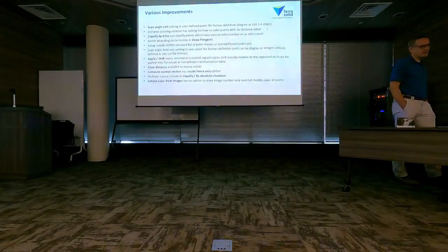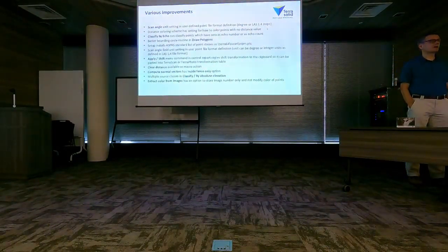process drone data and you have single markers and you solve an XYZ shift to match the data with single marker control points, when you do the apply shift, the software now places a transformation definition on the clipboard so that you can paste it into TerraPhoto transformation table or TerraScan transformation table.